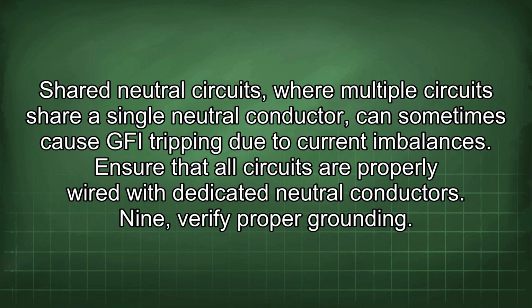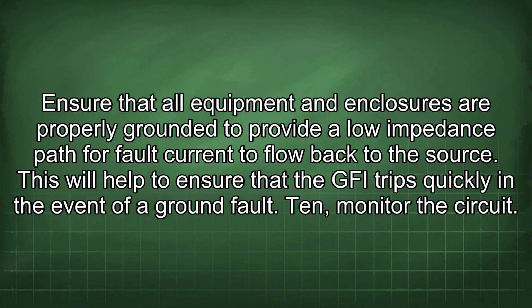9. Verify proper grounding. Ensure that all equipment and enclosures are properly grounded to provide a low impedance path for fault current to flow back to the source. This will help to ensure that the GFI trips quickly in the event of a ground fault.